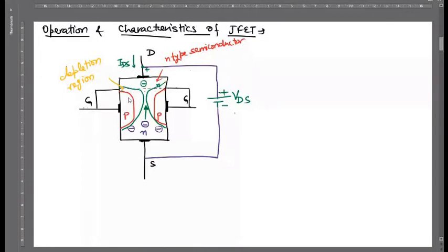You can see here, this is bigger at the drain side because this is reverse biased here, and electrons are moving in this way. So this reverse bias potential increases, and that potential affects the depletion region at the drain side, and that's why the width of this depletion region is thicker on the drain side. I hope you understood what I just wanted to deliver to you.